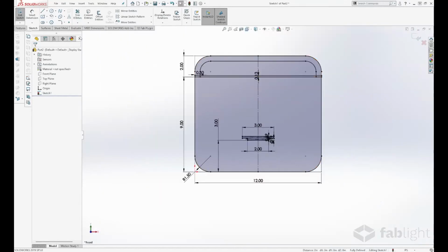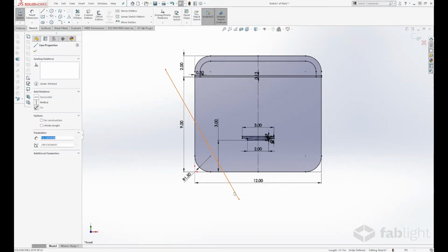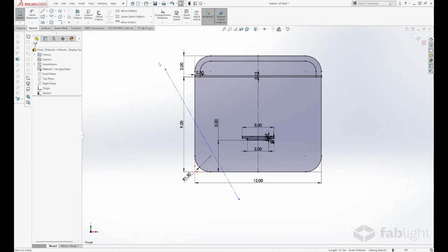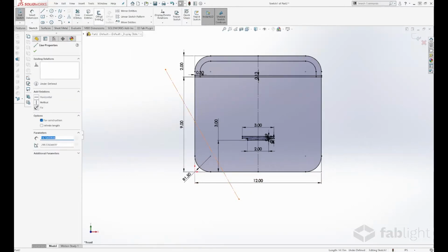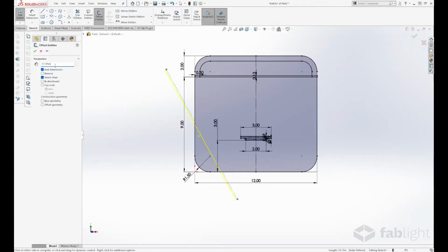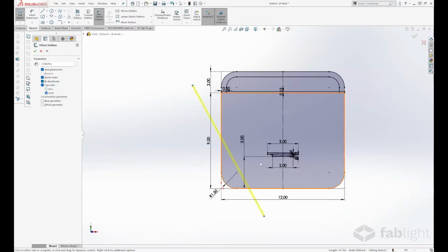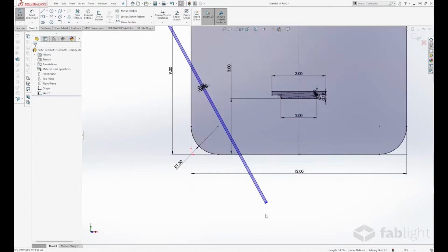Okay. So this next piece, we're actually going to start working on our sidewalls already. And so we're going to draw this center line. This is going to be our construction line, and we're going to call this our sidewall. We're actually going to offset this. So we're going to divide this by 2. That's the thickness of our material, and we're going to go bidirectionally. So that'll make our 1/8 inch material. And we're going to cap each of these ends. I'm going to show you why we're doing it this way here in just a second. So we're going to do that.